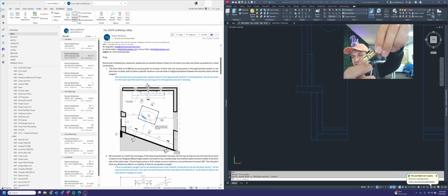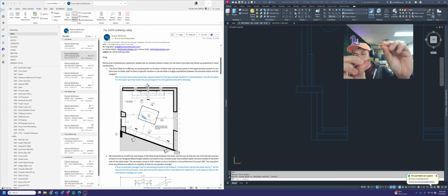But these are a brass piece of material. There's two parts. So looking at it, you've got a plate here and you've got a base here. Inside of the base, it's hard to see a little bit, but there are two bearings that sit in there. And at the opposite sides of those bearings, there's a flathead screw. The flathead screw allows you to adjust the tension on those bearings that are inside of there.